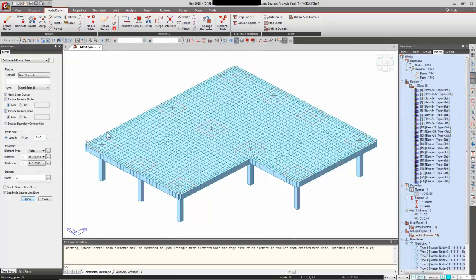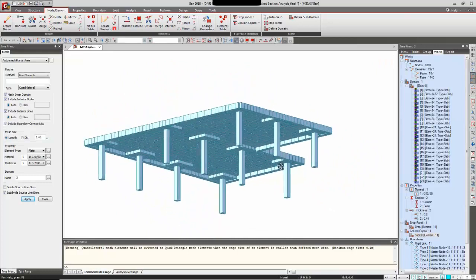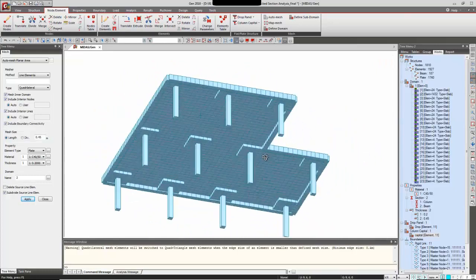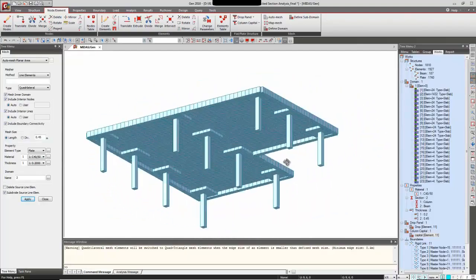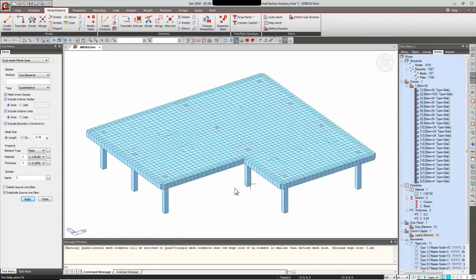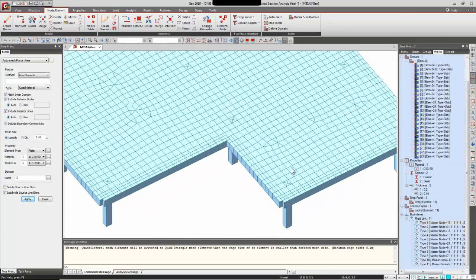After we click on apply, we can see over here at the bottom, this is easy dynamic rotation that I'm using by pressing on Control and the scroll button. So we can see over here that the drop panels are automatically generated. Let us also look at the rigid links that the software has automatically created. As you can see over here, right click, say display. These are the rigid links created automatically by the program.